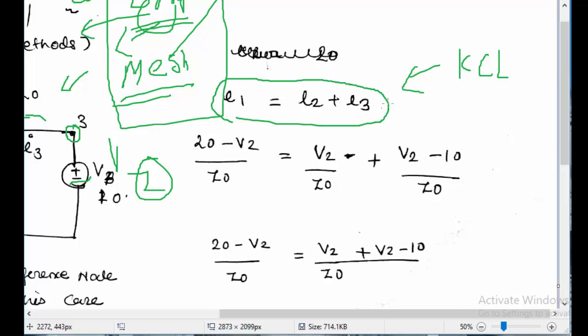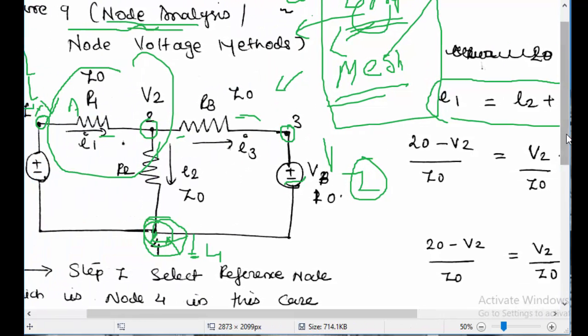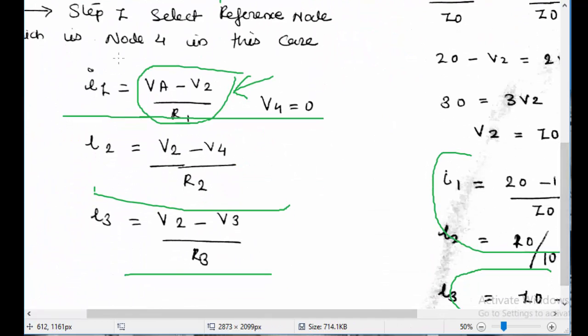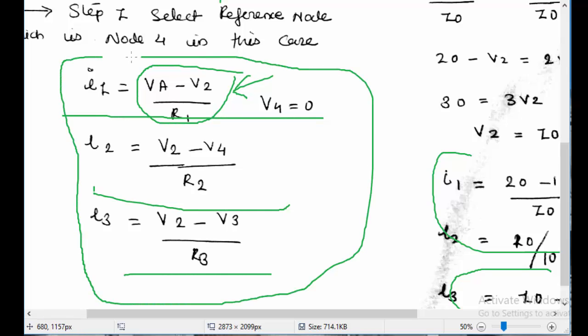You will need a minimum of two kinds of equations to solve the circuit. One kind is what you found by identifying all the nodes and writing all the equations for the currents using the voltage drops, considering the voltage at each of the nodes.